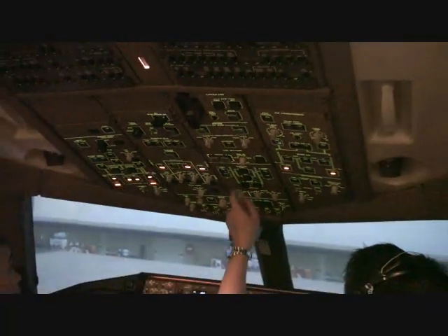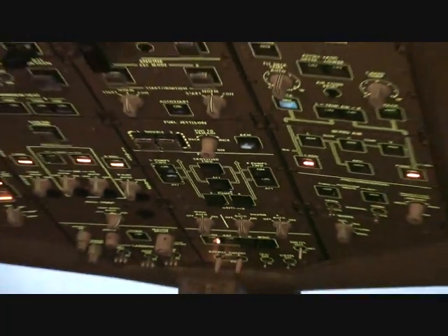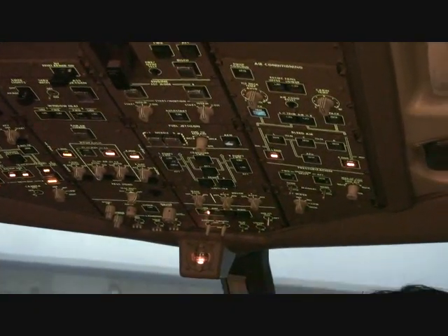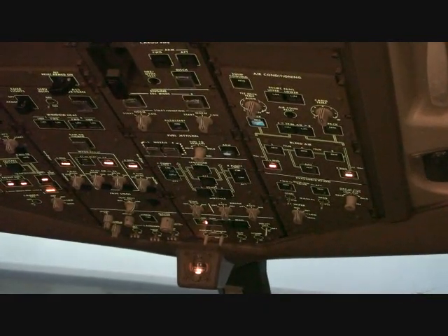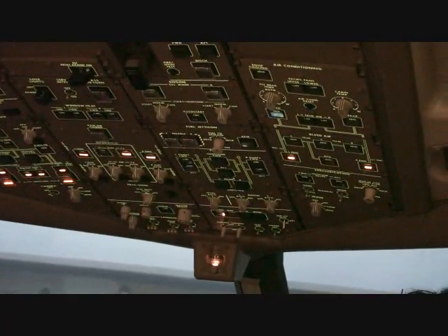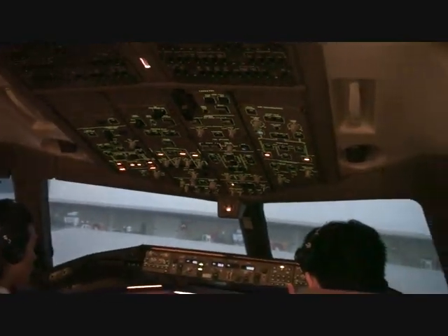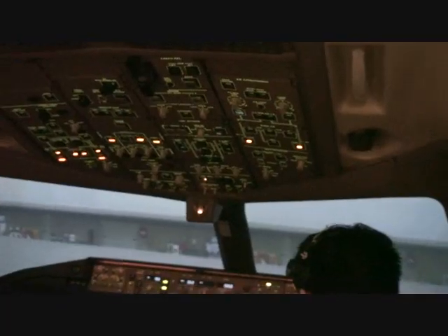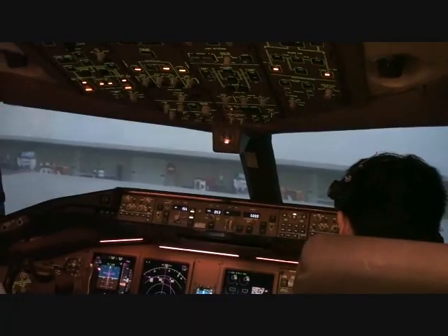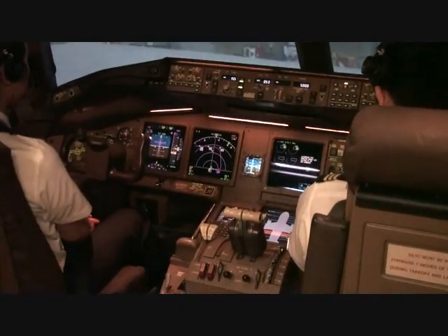Fuel panel set by CM2. Left and right fuel pump switches on. Verify that pressure lights are extinguished. For selection of center pump switches, there are variations between aircraft types. Cancel, recall switch, push, CM2. Cancel, recall switch, push again. Verify that only expected alert messages show, and verify that the messages cancel after the second push.